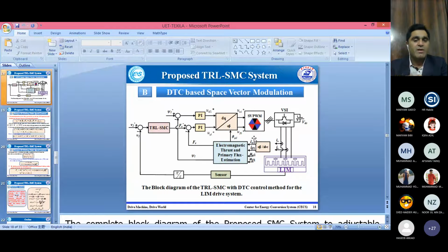In a practical system, what we have done in the lab, we can change this load by applying an anti-torque on the same shaft, load or torque, you may say torque. We produce anti-torque on the same shaft. One motor we control, and with another motor we produce a torque to check the different loads, just like this. Yes, thank you very much.